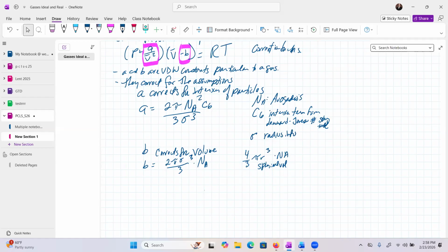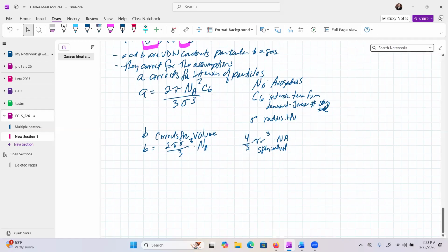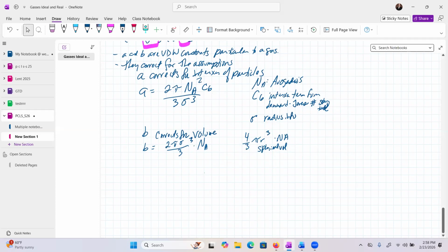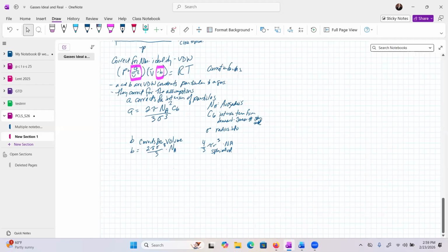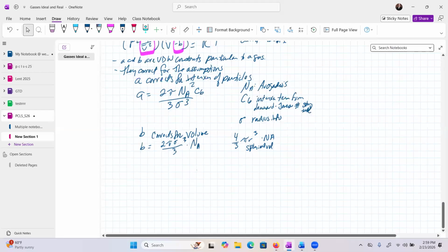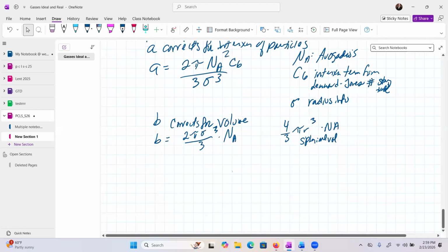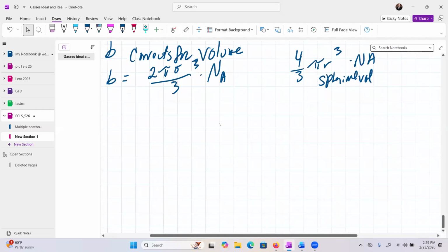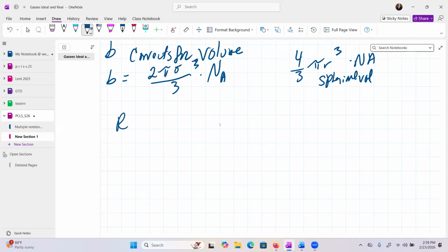So there is another equation of state, which is like a correction on the ideal gas, and that is called the Redlich-Kwong equation. And it works the same way that the van der Waals equation works in terms of what you would use it for. You would use it as a correction to the ideal gas equation when you had information about a real gas. There are also others. And one challenge I gave previous students is I let them make their own non-ideality equation, which you might want to do.